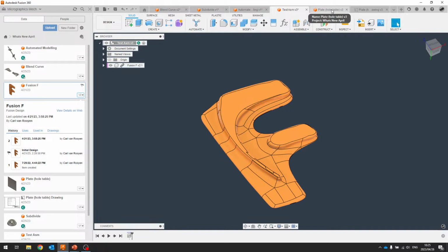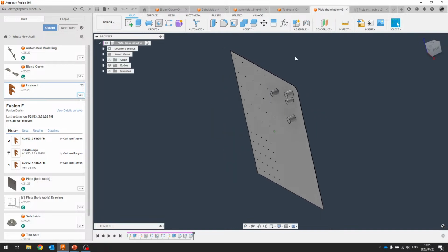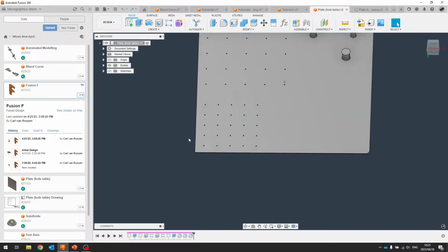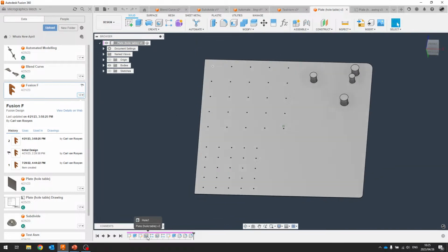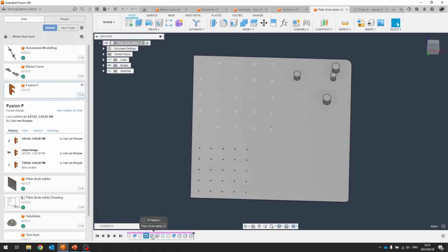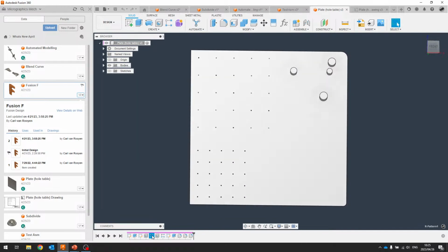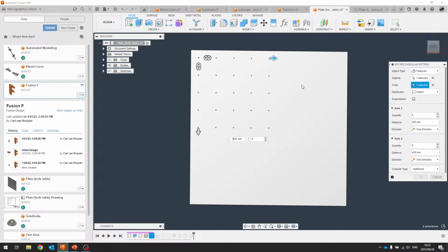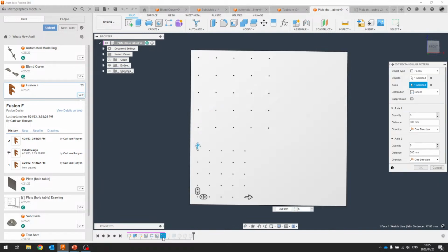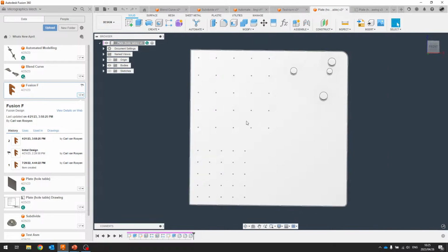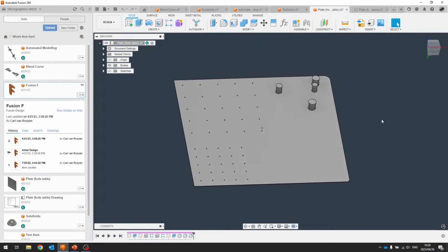Last one for this demo, we go to automated center lines. Under automated center lines, in this example here, I've got a couple of different things. Top left-hand corner, I've drilled a hole and patterned that feature. So the set of holes on the top left corner, those are featured holes, or a featured hole that's being patterned. The pattern is a feature pattern. I'm going down and confirm this. So object type features, where with the bottom left, that pattern, it's a hole feature, bottom left corner, but the pattern is for faces. This is just to show the different behaviors when inserting the center marks on the drawing.